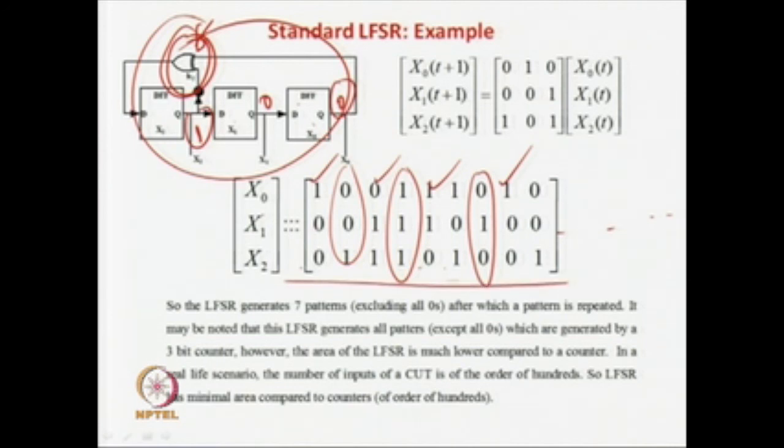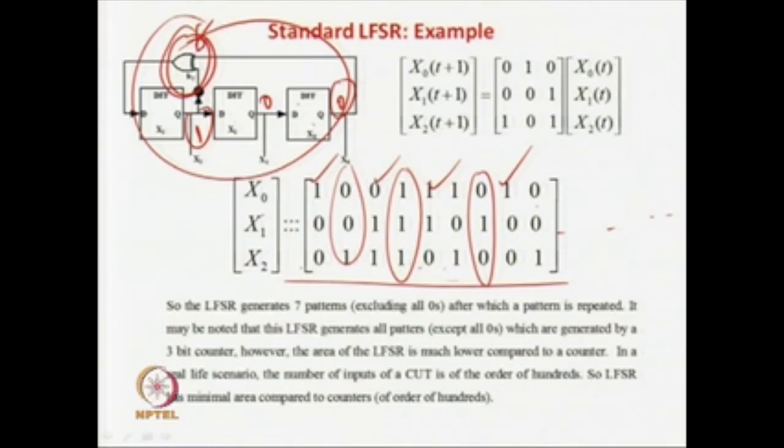But if you could have designed a circuit which would only generate this test pattern, the area would have been larger, but you could have done your BIST testing faster. But anyway, we do not have that area flexibility. But then what is the solution? Sometimes you can find some characteristic polynomial and some seed so that it will generate only these patterns or maybe 1 or 2 more than that, but you cannot always guarantee. That may be possible, which we are not looking at in depth in this course, but you can do that as an offline study.